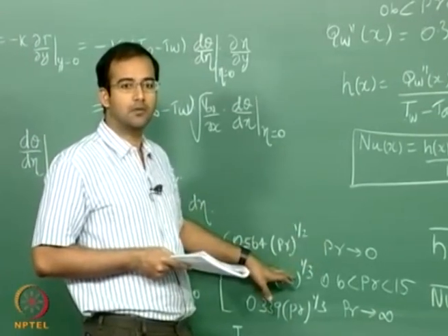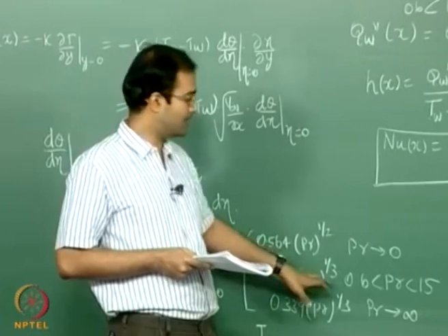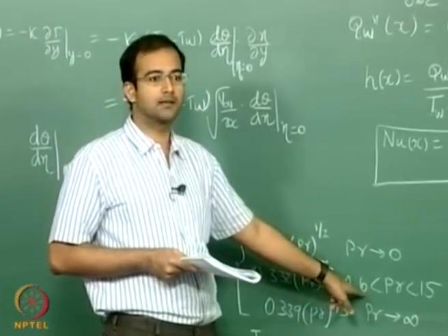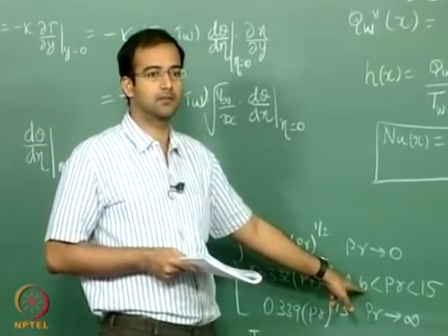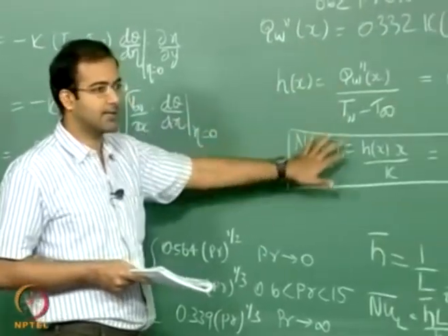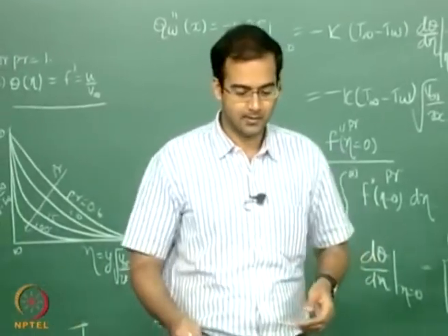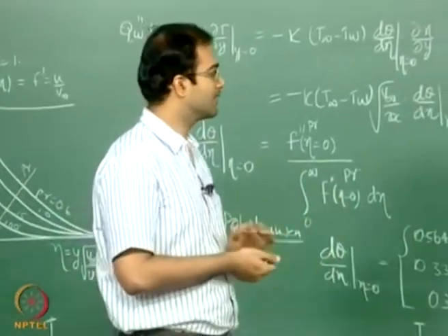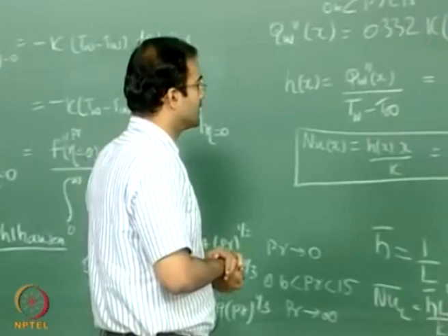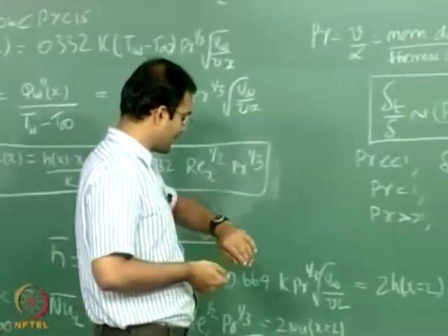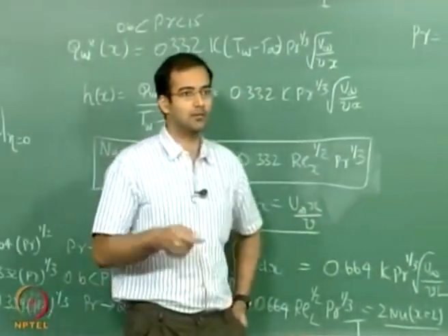Most of the practical fluids, air, water and so on, fall in this intermediate Prandtl number regime. That is why we have specially derived the expression for Nusselt number for the majority of the fluids which fall within that Prandtl number range. Okay, in fact this will also be a very nice exercise which I can give you probably in your